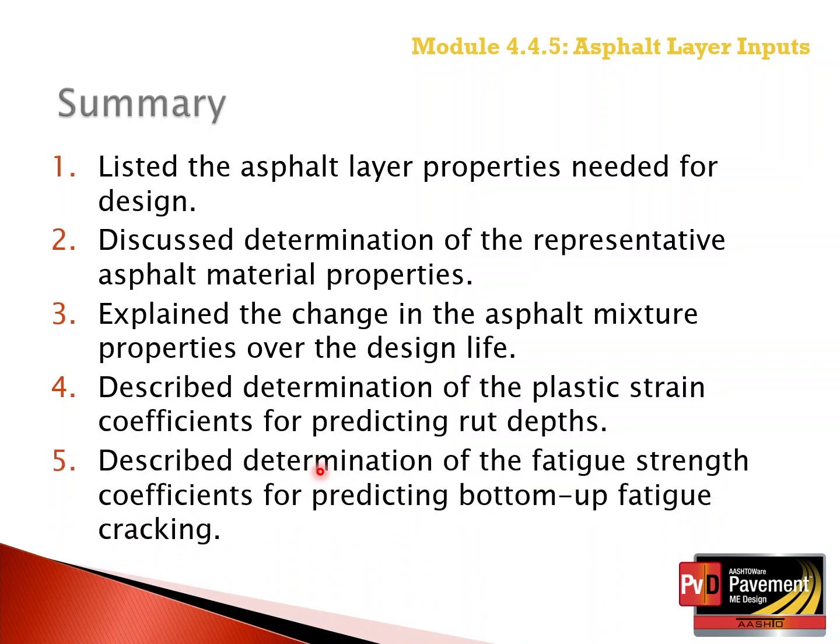The fifth and final outcome was to describe determination of the fatigue strength coefficients of the bottom-up fatigue cracking transfer function that can also be measured in the laboratory via the AASHTO T321 bending beam flexural test and or the surrogate indirect tensile failure strain test, ASTM D6931, and a dynamic modulus test of AASHTO T378.